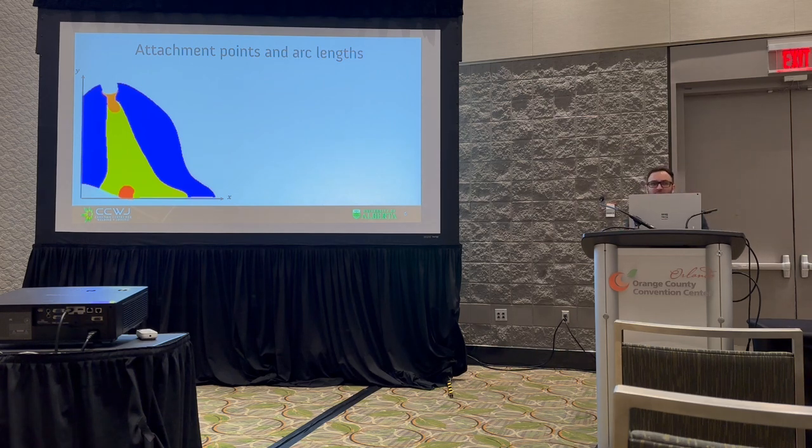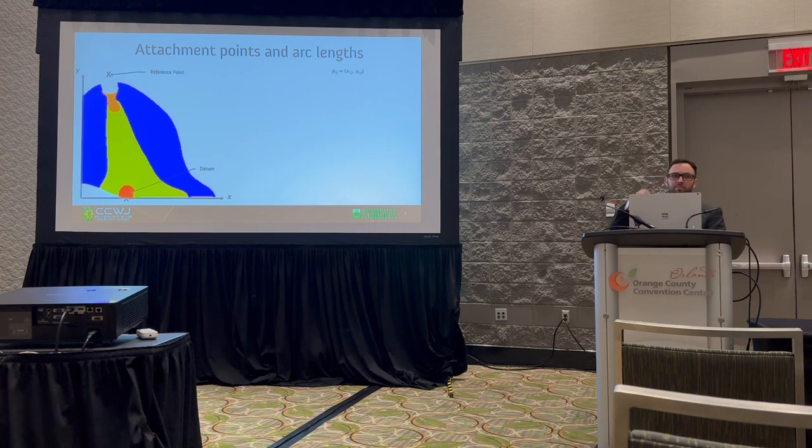Now, how about distances? To measure distances within the arc, you need attachment points. We're putting everything on a coordinate system, so every attachment point that we define will have an X and a Y coordinate. The way we developed the software, we have a user-defined reference point and a datum point. The reference point is a user-defined point right above the molten consumable, in the middle of the consumable. The datum is the location where the droplet comes into contact with the weld pool.